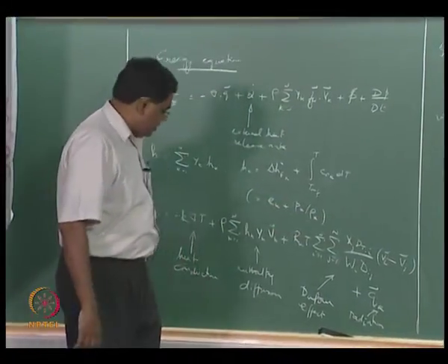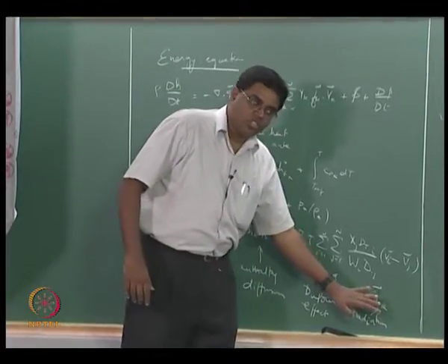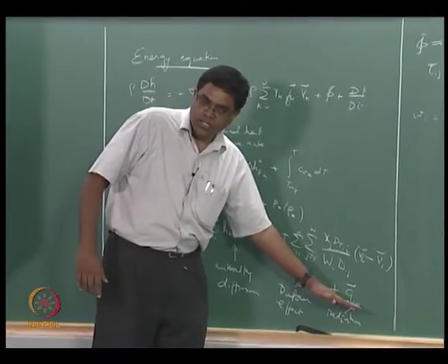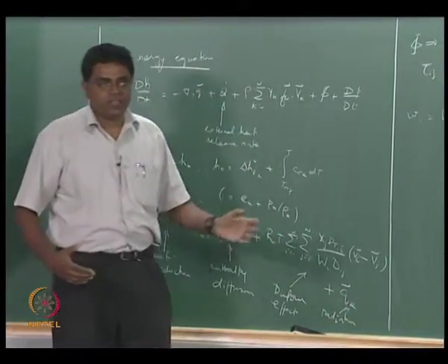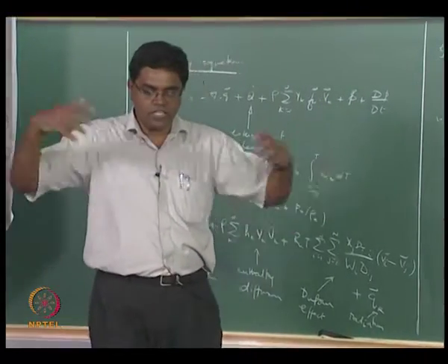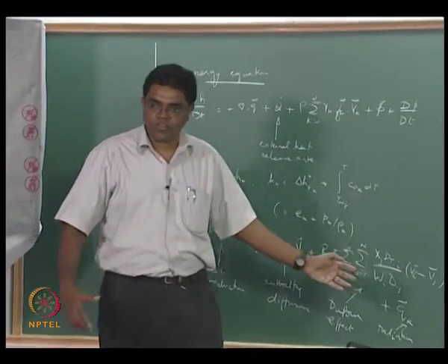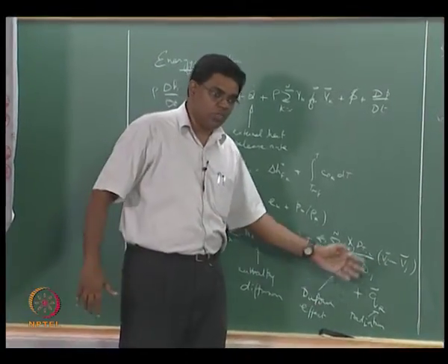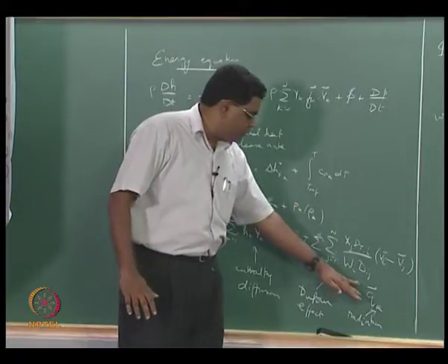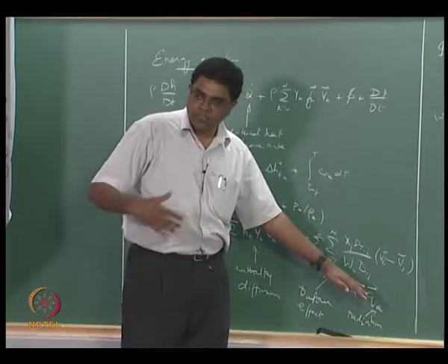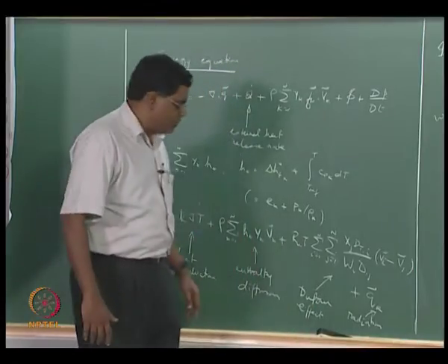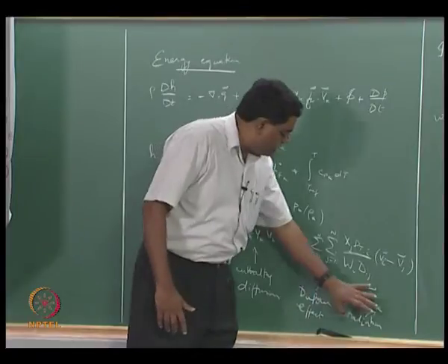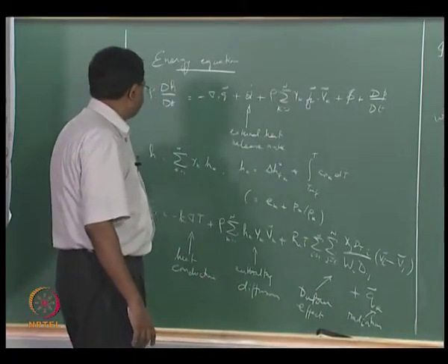QR is a general term that's been written out to take into account radiative heat flux, alright, but you should now be able to expand this, taking into account things like shape factors and emissivities versus absorptivities and all those things for the surfaces as well as gases that are involved in a volumetric or surface manner and so on, with a T to the power 4 dependence, putting in the Stefan's law and all those things. So if you want to bring radiation into account, there we are.